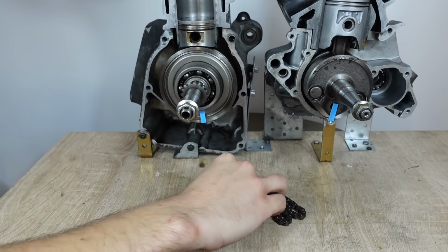Now, if we move over to the two-stroke, we can see that it replaces all of this with just this. In the case of the four-stroke, this is the cylinder head together with the valve cover, whereas in the two-stroke, we really have just a cylinder cover or cap. There are zero moving parts. No valves, no chains, no cams, no springs, and therefore less weight, less complexity, less cost, and less potential for failure. So then how does the two-stroke get gases in and out of the cylinder without valves?